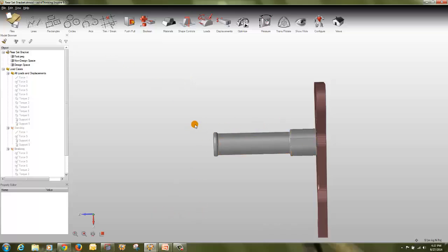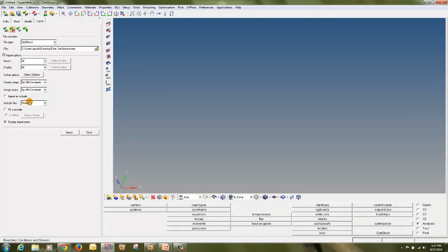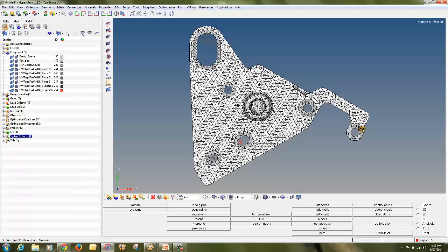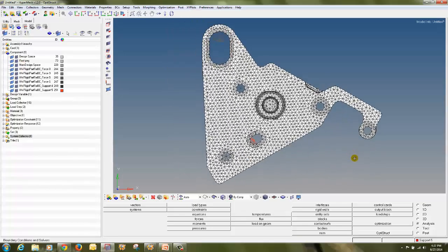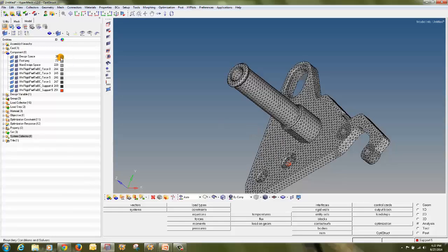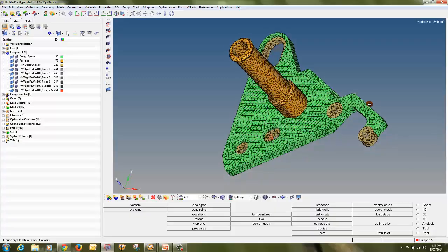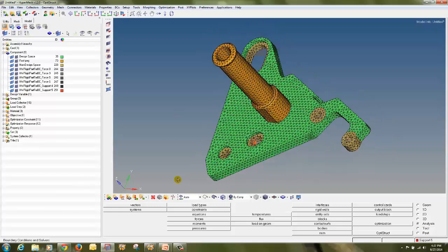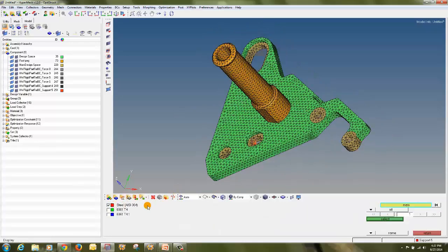Lastly I will show you that I have exported that file into FEM. So let's open HyperMesh and import that file. I'll select that file, import to optimization, close, hide the load cases, hiding the system. So this is the model with a design space, with all the different components and with proper meshing done already. With the rigids and all, it already has everything. The material you assigned, it will have that material also.